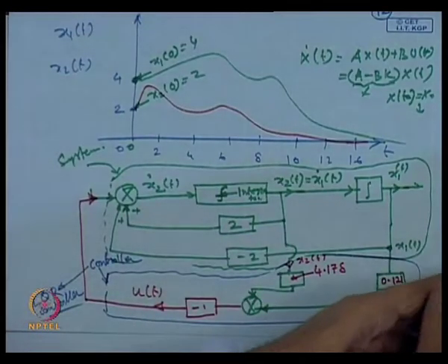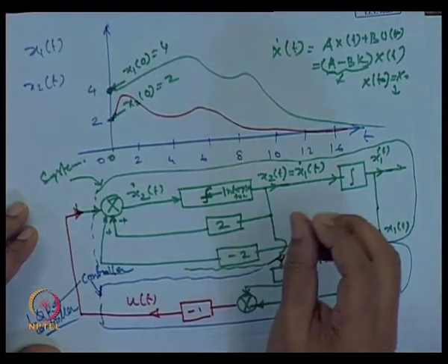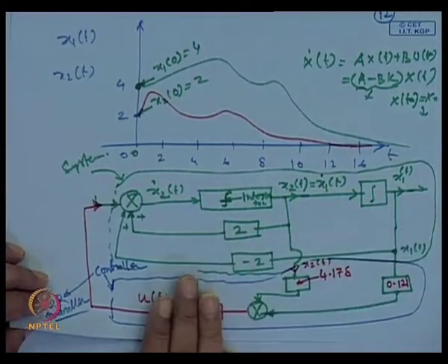So, one can look at this expression, one can change the controller gain by selecting the state weighting matrices Q and R. These are the only tuning parameters the designer has. I can tune the controller parameters, the K values, by tuning Q and R. So, as long as our response is not satisfactory, we can always tune Q and R to get the desired response. So, this scheme is the infinite time LQR problem solution.